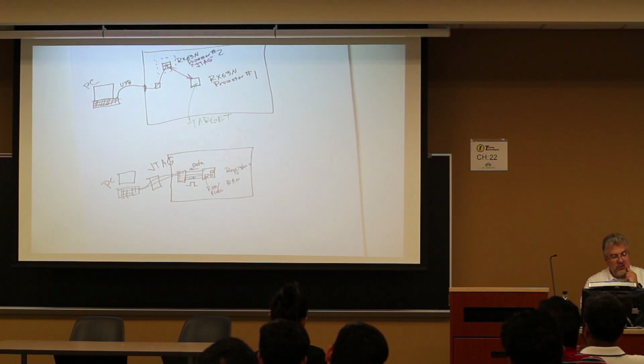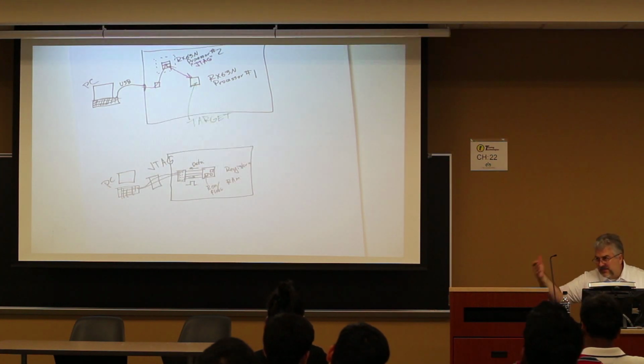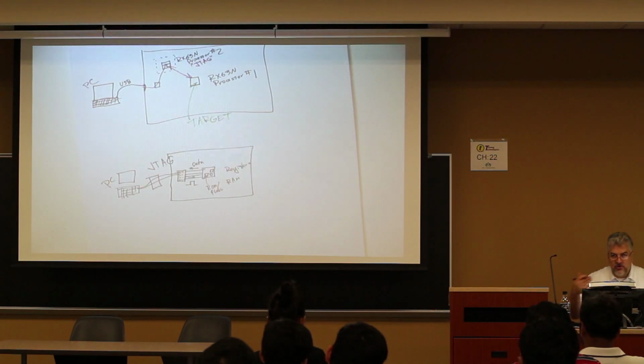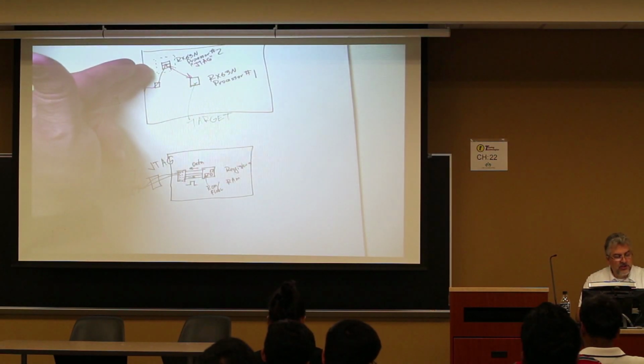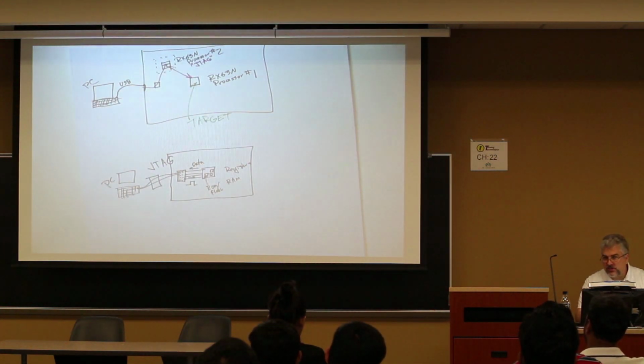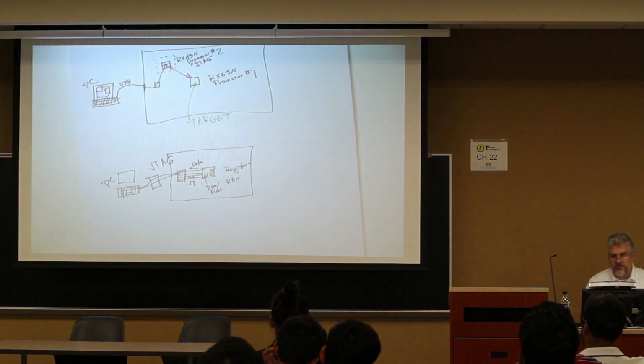And so the instructions of let's run this processor step by step by step is actually controlled by this processor. It only allows that one to run step by step by step. And it's also grabbing the information about the contents of registers, the contents of RAM, and passing that back to the PC, which has on its screen all of the wonderful things that say this is the contents of RAM, and allows you to stop and go.